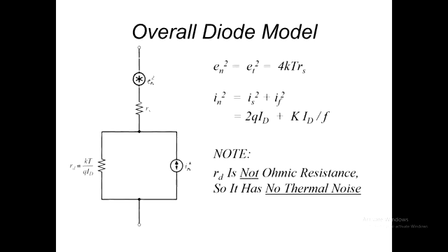And there's also a conduction pathway to where the action's going on in the diode, the junction itself. So it's what they call a bulk resistance. So that's a real resistance, and it's present all the time. And there will be noise going on in that, even if we've got nothing connected to it. If it's not at absolute zero, there will be some thermal noise associated with that resistance.